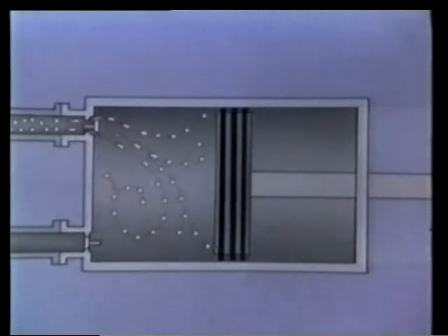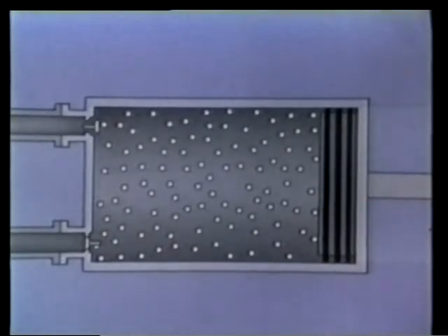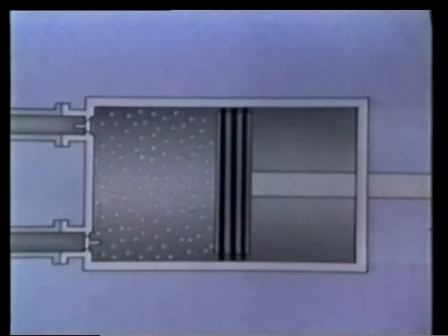In its simplest form, a reciprocating compressor consists of a cylinder, a piston, an inlet valve, and a discharge valve. As the piston moves on the downstroke, the space it occupied is temporarily at less than atmospheric pressure. The higher pressure outside pushes the inlet valve open, allowing air into the cylinder. On the upstroke, the inlet valve closes, and air is squeezed together, raising its pressure and forcing it out through the discharge valve.